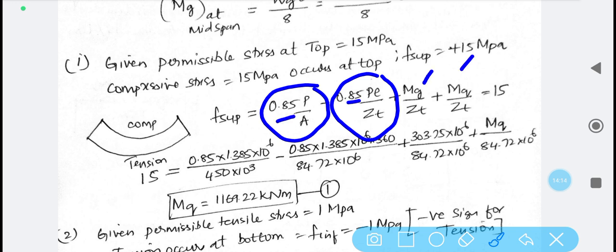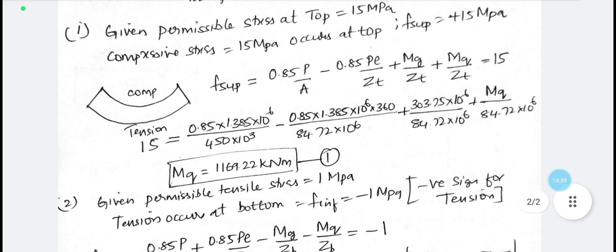And here there is no multiplication, because when it is subjected to loading or service conditions, losses are accounted for in the later phases. So in the preliminary phases, the losses during pre-stressing have to be considered for the direct stress and the stresses developed due to bending. After substituting everything,